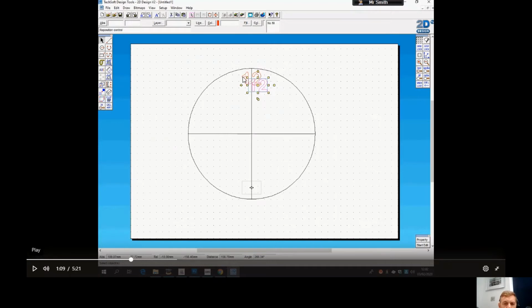If you decide that you want to cut the number all the way through, then you can keep it as black, and it would cut the number all the way through. And the other option is to copy the number, move it outside of the circle, and it will engrave the 12 into the clock face. But then you can also cut out the numbers separately and then stick them on afterwards, so they look like they're sticking out from the page. So you could put the 12 outside and just change that to black, so it cuts the number out separately. You can do a few different versions.